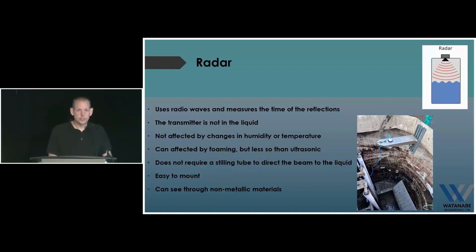But the big thing that we're finding is that the cost of these things is coming into play. You can actually put a transmitter in for less than $2,000 now, so that's very comparable to the float switch type applications. You still do need your controller to be able to control your pumps as well, so you have that little bit of extra cost in there as well. But it's becoming very comparable to a relay-based float switch system.